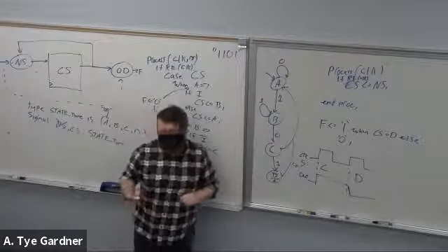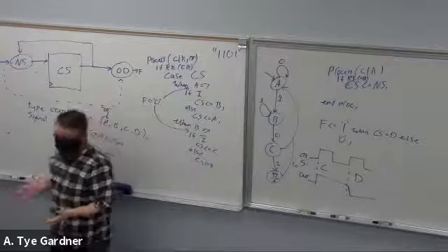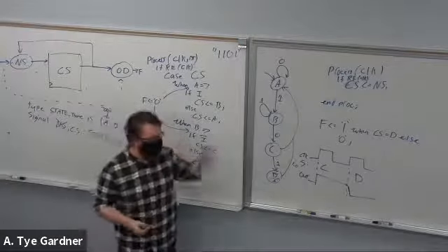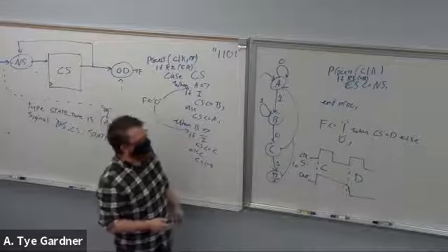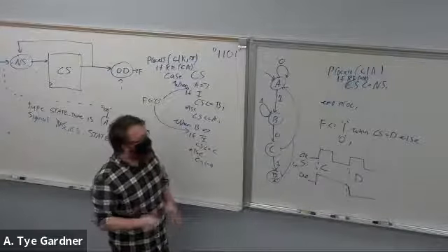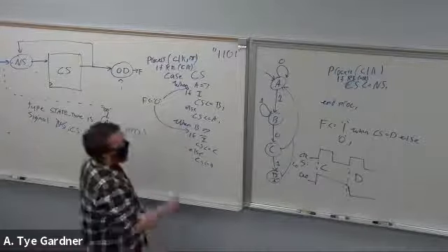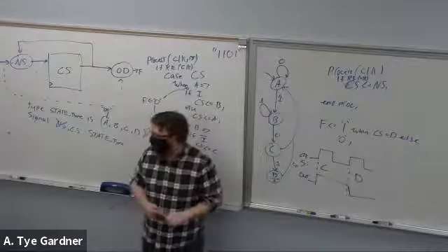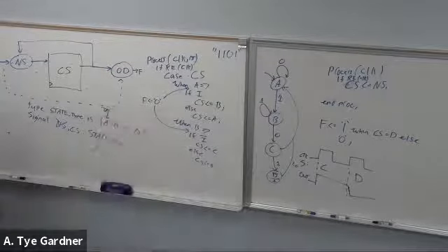A sequence decoder is actually really common in state machines, and it's a really common homework assignment. I'll certainly give you one coming up this week. The way that I suggest making them, if I want to detect 101, is start by making the path that you know is what you want. And if it's a Mealy machine instead of a Moore machine, I'm actually just going to erase this code. I think you're okay here.